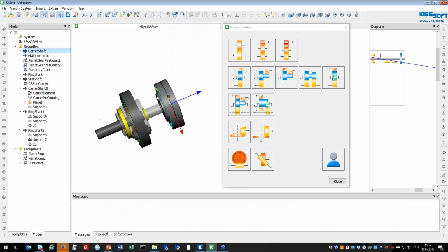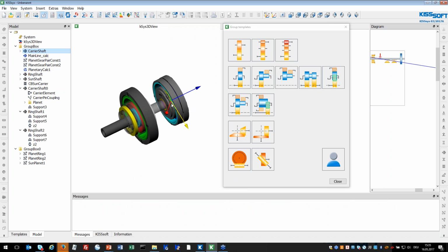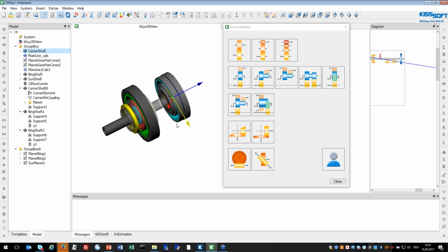Just by making a refresh, also the planets will be positioned, and we have our two-stage planetary gearbox already, where we have already also a Wolfram stage for the second one. So in this way you can combine all different predefined stages, and the procedure would be the same now to add the couplings and defining the kinematics, calculating the operating conditions first, and then calculating the strengths in the system. So there is a big update for complex models which can be used. So this is first part for the handling.